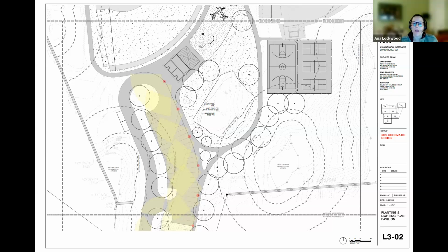Okay. And the further you go in and the further you run your lines, the more expensive it gets. Okay. So a good compromise that we've done in the past is during the construction, you put all the conduits in, so you don't have to dig again later. And if we don't have the money now, we could add lights later on because the conduit's there and you can just pull the wire. Underground is typically the best way to handle something like that.